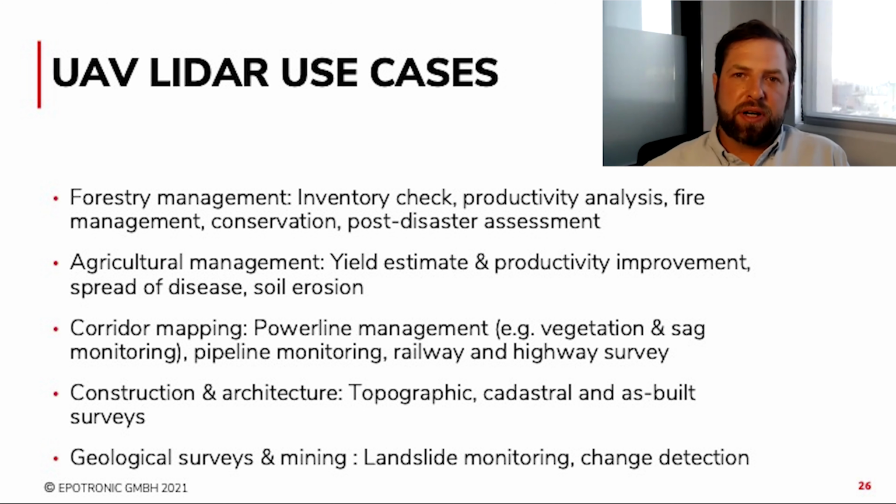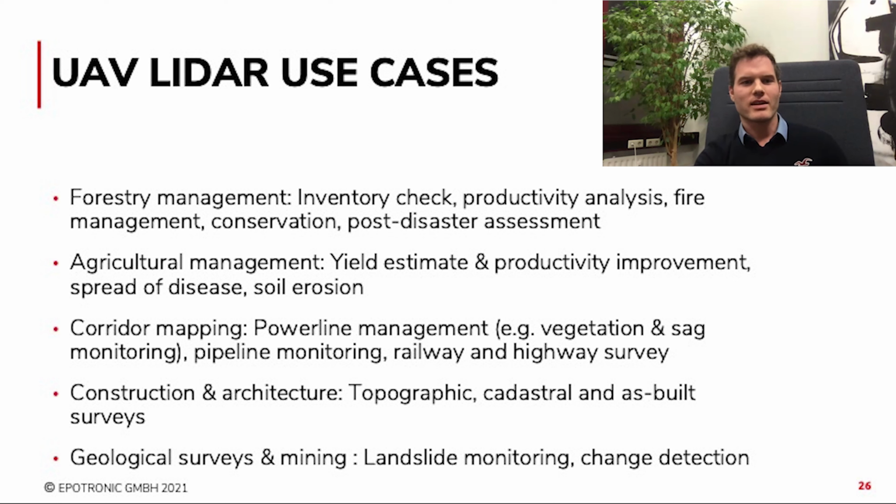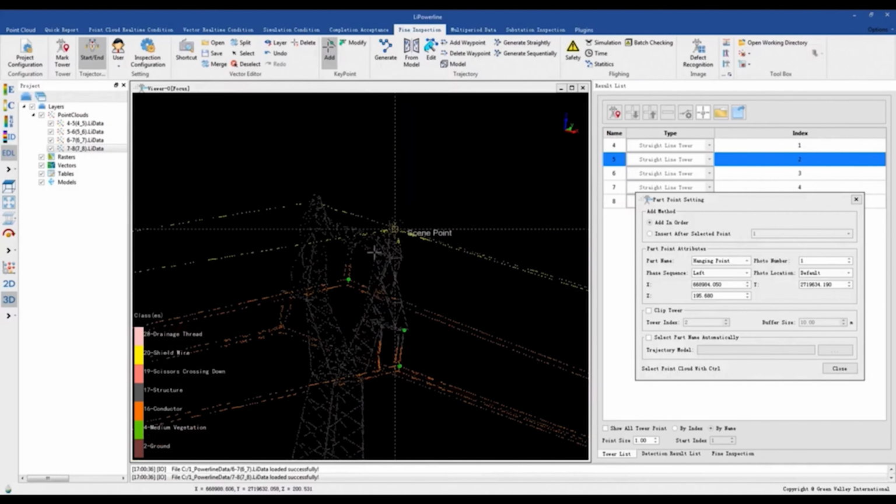Yeah, that's a cool technology. Also for corridor mapping, so like power lines, I've seen LiDARs flying 1.5 years ago in China by a lot of Chinese power grid companies, using something like the LiDAR V back in those days. Now it would be the V70. So they are essentially also doing vegetation monitoring with it, but also the sag measurement. It can be done by photogrammetry maybe these days, but I would say if you're doing it on a large scale and not on a pilot project type, the LiDAR will really pay off. We'll show you a bit of an example.